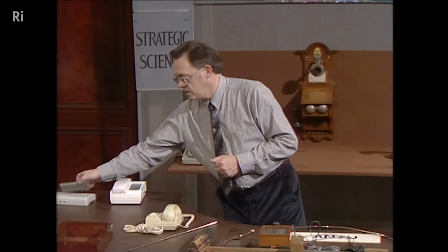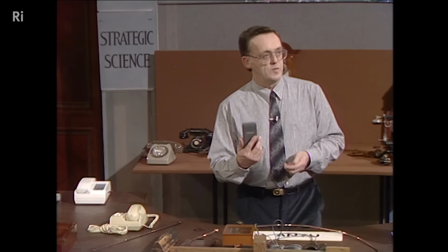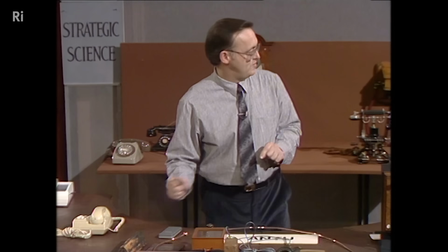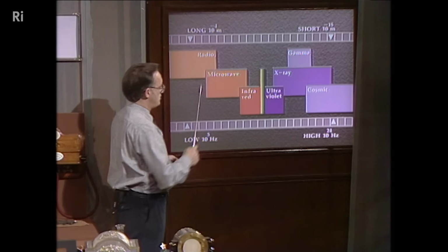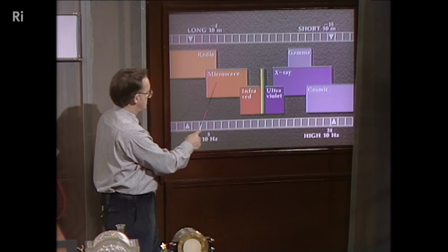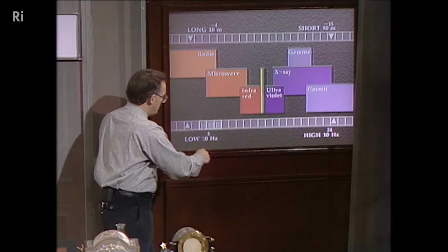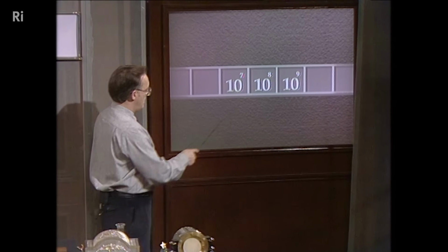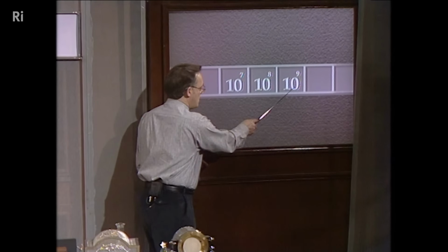And we'll be using, instead of this phone, which I'll call a CT1 phone, a much more portable phone called CT2 phone. Let me explain to you the basic difference between them. I've shown here the electromagnetic spectrum. And the region we're interested in with cordless phones is in the radio microwave region, in this region down here. Now let's just blow up that region there. We're talking about frequencies in the range 10 megahertz to 1,000 megahertz.